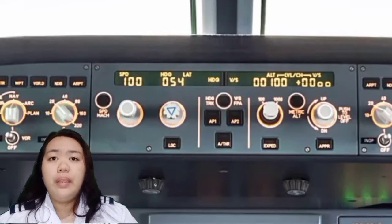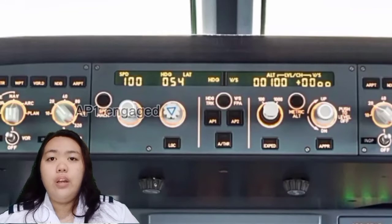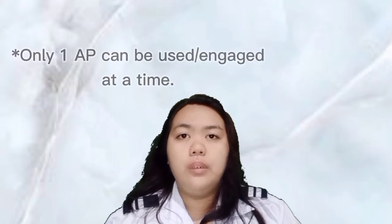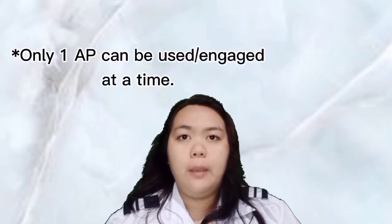If you're wondering why it is connected to the aircraft's altitude, it is because the designated button will use the altitude data of whichever autopilot is engaged. For example, if autopilot 1 is engaged, then the transponder will use the captain's altitude data. Even though there are two autopilots, only one autopilot can be engaged at a time.